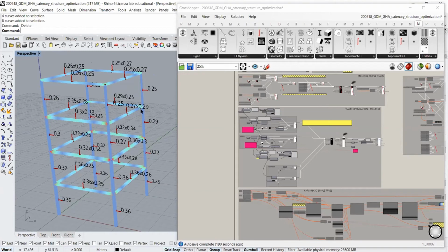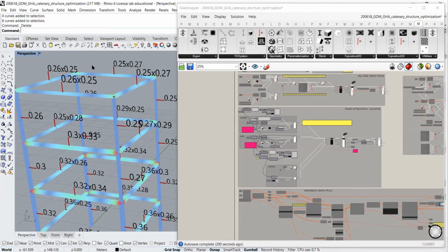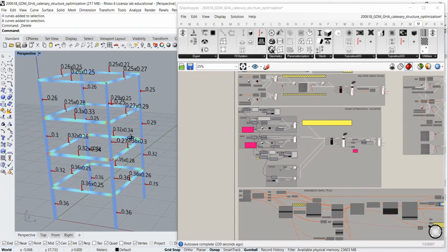I think it's not healthy to think about creating four different beams, one measuring 26 by 25, another one exactly the same, and then you have 25 by 27, 25 by 27. Of course, this from the analytical point of view is perfect, okay? But this also means that you must create customized beams at each level of the structure. So it's unhealthy somehow, or anti-economic.